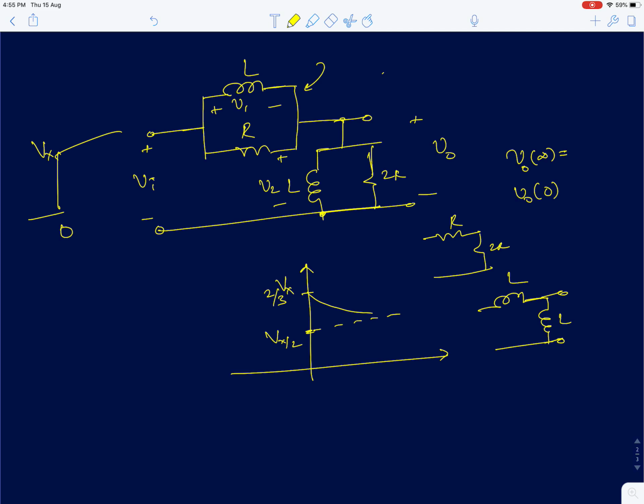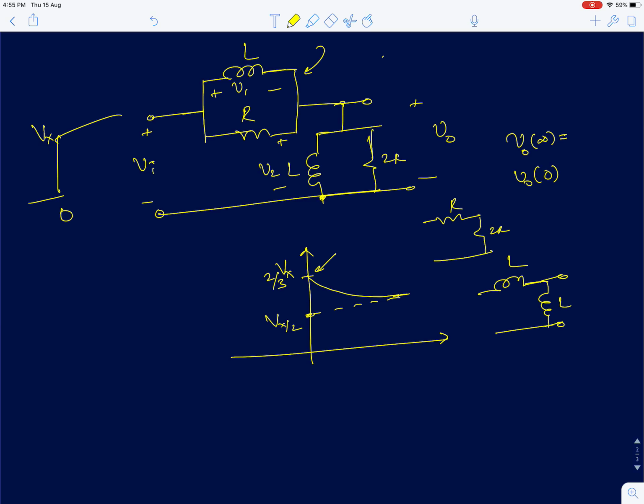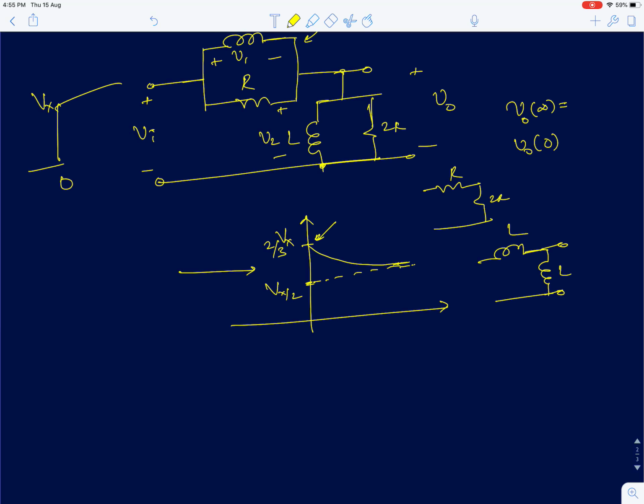And the system is going to finally reach the steady state value from the high frequency value. Again, we have already seen when you can have a response like this. If your initial value is greater than the steady state value, then usually there is a 0 and a pole, and the 0 occurs first, then the pole. We can say it from that, or this is also a leading phase system. We can best look at the transient response and say that. I've already discussed what a leading phase system is extensively when we spoke about first order RC circuits. You can go through those lectures.